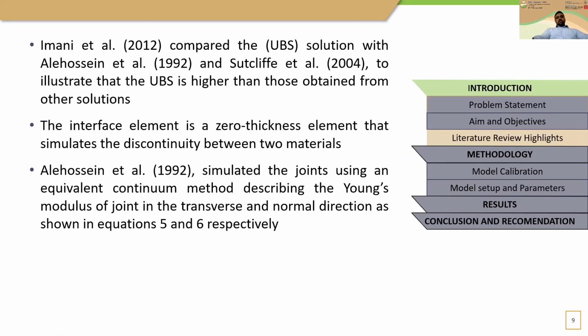Iman et al., Sutcliffe et al., and Alwis et al. all considered jointed rock masses and how to simulate them. Iman et al. used the discrete element method, while Alwis et al. and Sutcliffe et al. used the finite element method, and Iman et al. considered the upper bound solution. The interface elements in the software we're using, Midas finite element software, are zero thickness elements which represent the discontinuities between two materials.